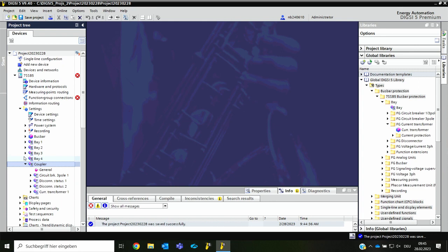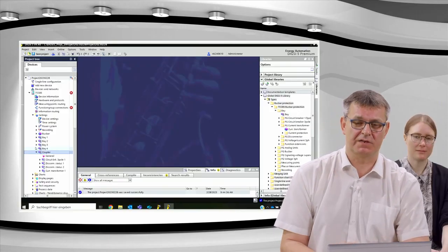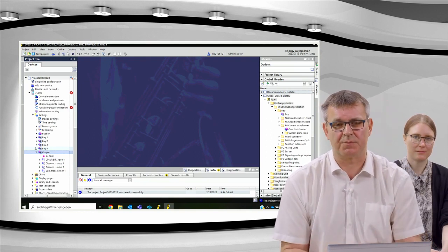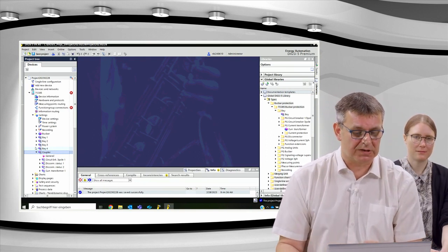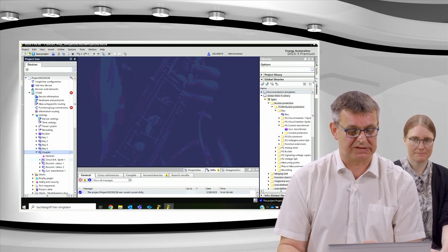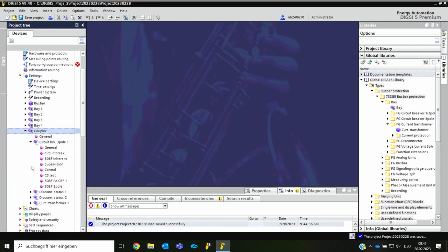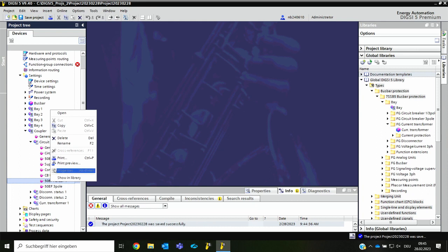Of course, we need the inherent circuit breaker failure protection, which will be started by a trip of a busbar protection anyway, but you mostly don't need an externally started one. Sometimes there are special configurations where we will also have an external start. But let's do here in this demonstration the most common things. And I will delete the external circuit breaker failure protection.